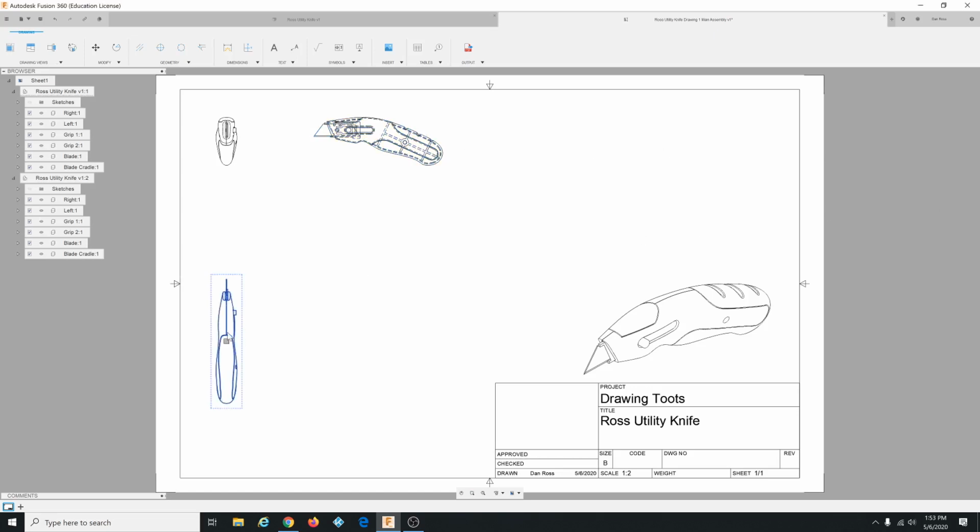If you double click the bottom view to edit it, you get the dialog again, and we could display what they call tangent edges, which is a way to treat, well, just what it says, tangent edges. There's more about that in the tutorial, but I want you to turn that on, and so all of these lines that designate where two tangent faces come together, basically that's a tangent edge. And click OK to close that.